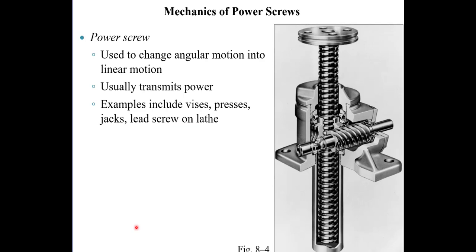We started this video off with an animation of a power screw with a nut on it, and this is another example of that. This is a device that takes this worm over here and it meshes with a gear that is fixed so that it can't move. So as the worm rotates, the gear rotates and moves this power screw up or down. And that power screw then can be used to exert a force and lift a load.